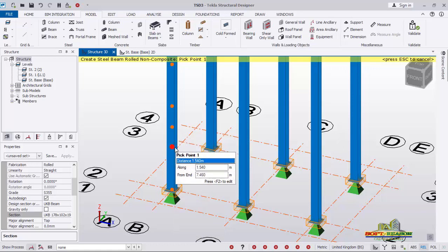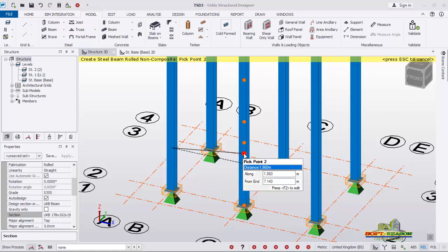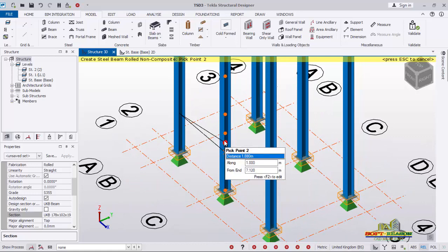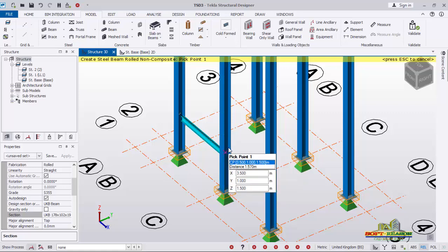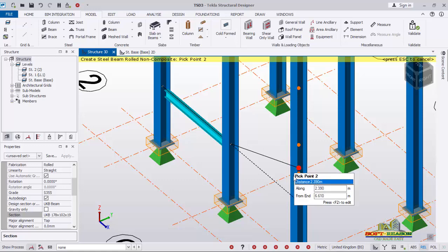So holding this over the steel stanchion, you can just press F2. You can see what happened in the provision where you're supposed to type the figure. It's been highlighted. Then you type 1.5, just like that. Then hit the enter button. It will pick the point at that 1.5. So you now extend it to the next column in the same direction and fix it there, just like that. Right? So you continue, you pick there to the next column.